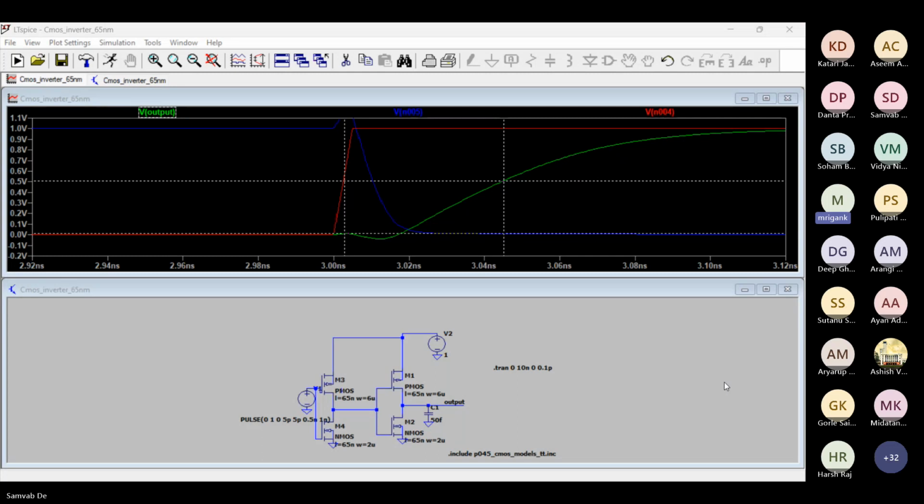And when VDD becomes too small and you start operating in subthreshold, we will discuss subthreshold operation in more detail. That is when you have an on voltage lower than VT or close to VT. In that case, the MOSFET equation becomes exponential. We don't have the square law any longer. We will discuss all that. So the reduction in current will become exponential. Either it is reducing by square law or exponentially. Therefore, the delay will increase.